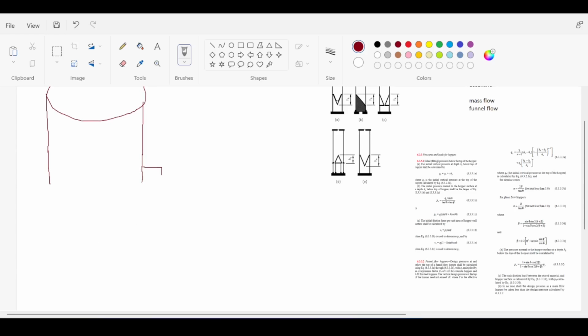Why? Because if you have an opening on the side, let's say that you have a silo that looks like this, and you have an opening on the side. Well, you fill the silo with your granular material to the brim. When you open this, the material will start to flow. However, you will see that only this material gets extracted out of the silo and the rest remains static. It doesn't move, it doesn't change. And even over time, it might harden and will be very hard to clean. So for granular materials, usually we have our openings in the bottom of that silo. So this might work for liquid silos, but for granular silos, that is not even an option.